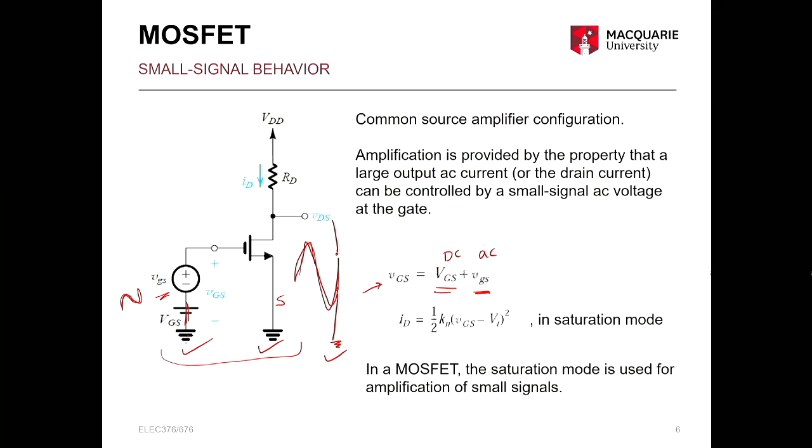So if I don't speak, that amplifier is still on, that current is still flowing, it is dissipating some power or producing heat. So the moment I speak, that is creating this small signal. That signal is picked up by the microphone, which is really tiny in amplitude compared to the DC applied to this system. And when I speak, all the amplifier is seeing is to amplify my voice, not the DC.